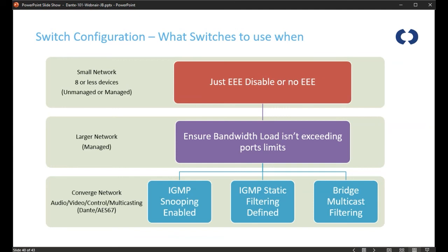So if you are aware, it's a really good idea to monitor the load on the port, not the Dante part of it, so not the one you see in Dante Controller, but what you would see on Cisco switch management or SNMP, to make sure that you're not going over the 100 megs that those little Ultimo chipsets can handle. Anyway, moving on to the next part of this.